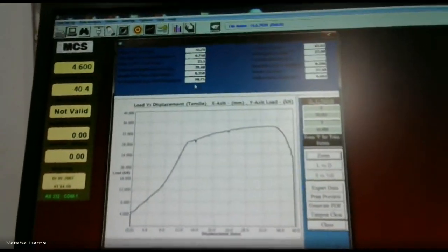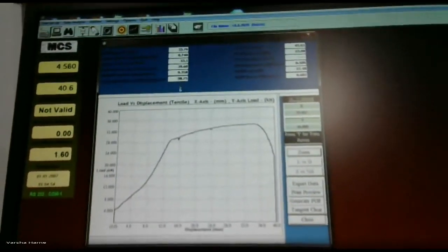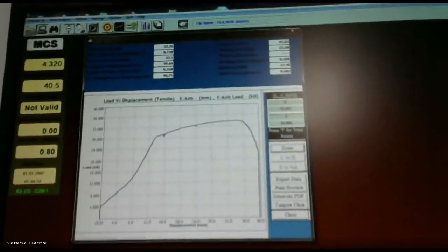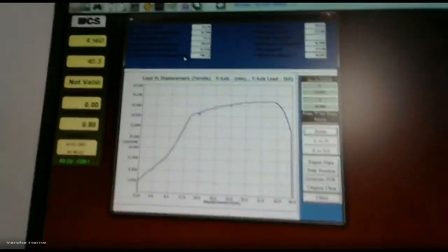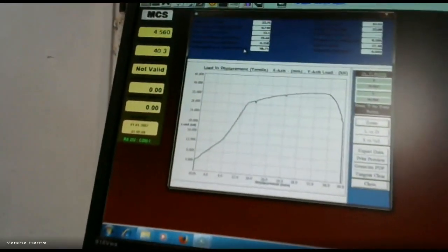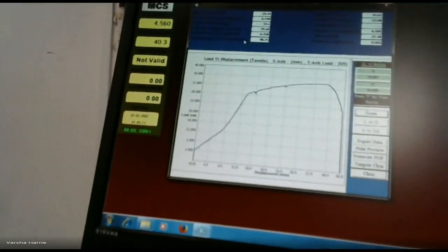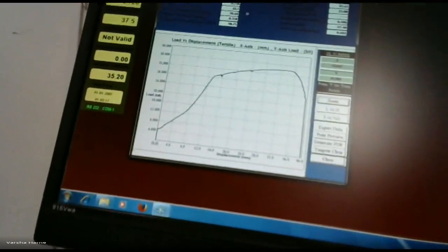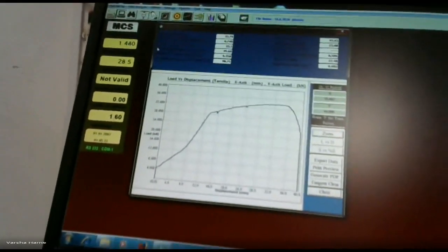Now see here the percentage of elongation with respect to gauge length. Today it is wrong now because we didn't measure our gauge length. We have to measure it first, then put in the value, then check the percentage of elongation. But normally, according to our IS, that percentage should be 25%, okay, 20 to 25% within the permissible limit. If it is there, then we can say that our bar is passed for construction. Clear? And we have to check here the yielding stress, yielding load, breaking stress.